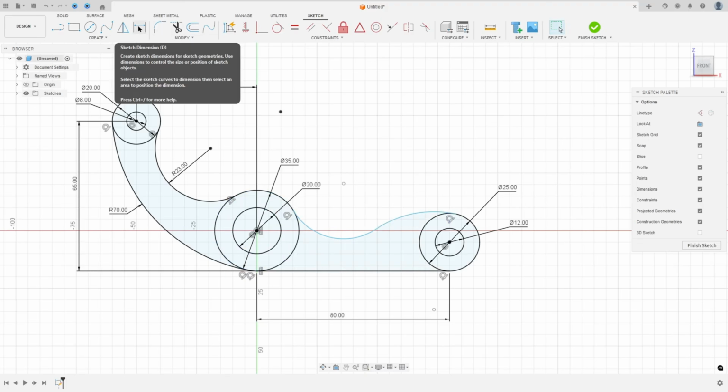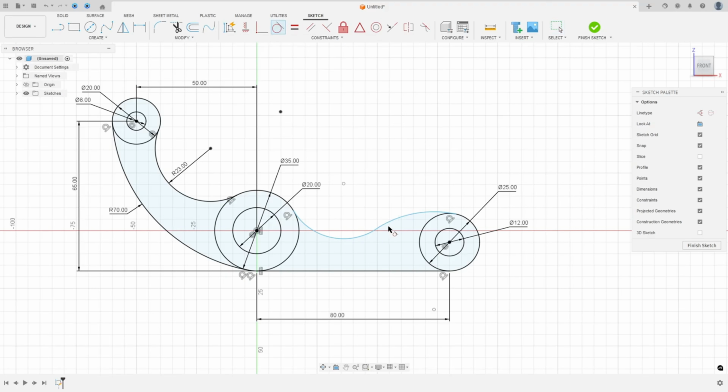Go to constraint, select the tangent, make this arc tangent. And go to sketch dimension. The radius here, 35 millimeters of radius, and the radius here, 130 millimeters of radius. And now click with the right button, select the pick circle arc tangent, select this arc here and this line here. The distance here, 13 millimeters. Okay, we made this.